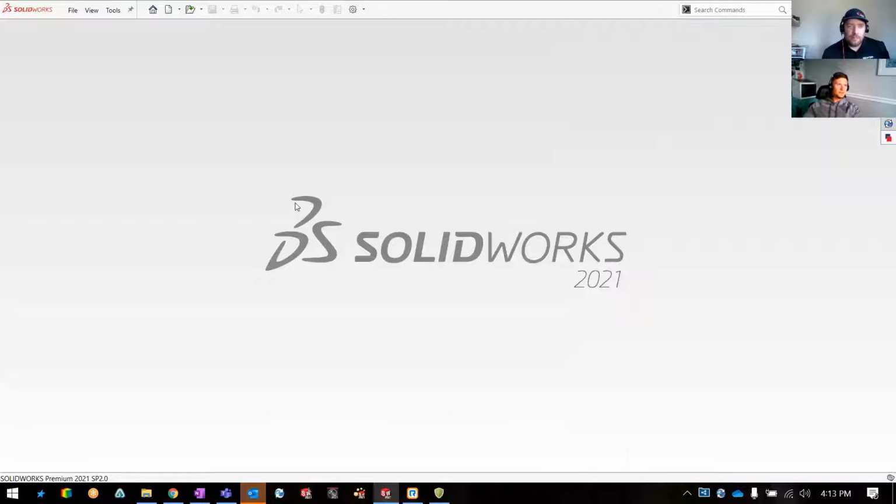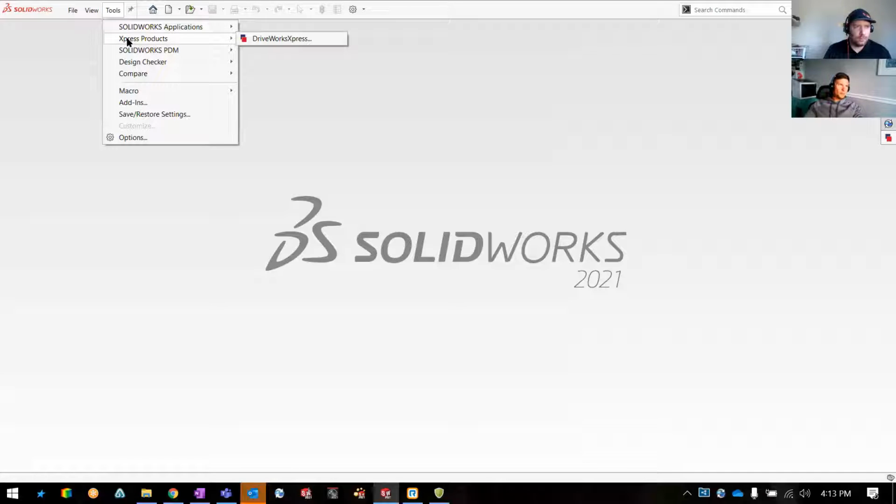So Brandon, do you want to show a quick example of how it sort of works? Yeah. Real quick, if you go to your Tools menu, head up to Express Products, you'll find DriveWorks Express right there. The thing that confuses a lot of people is that if you haven't opened this tool before, it's going to show you a little activation window. It confuses people because they think they don't have a license for it. Well, it's included with your SolidWorks license. You just have to follow the link and get the activation code. It'll just want you to log into your My SolidWorks account to do that. It's pretty easy. If you get hung up on it, our support team can help you out. But it only takes a couple seconds.